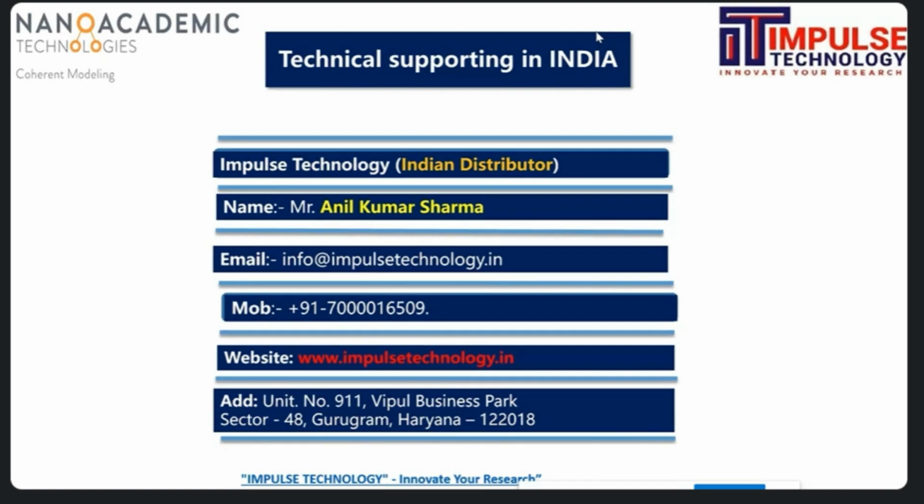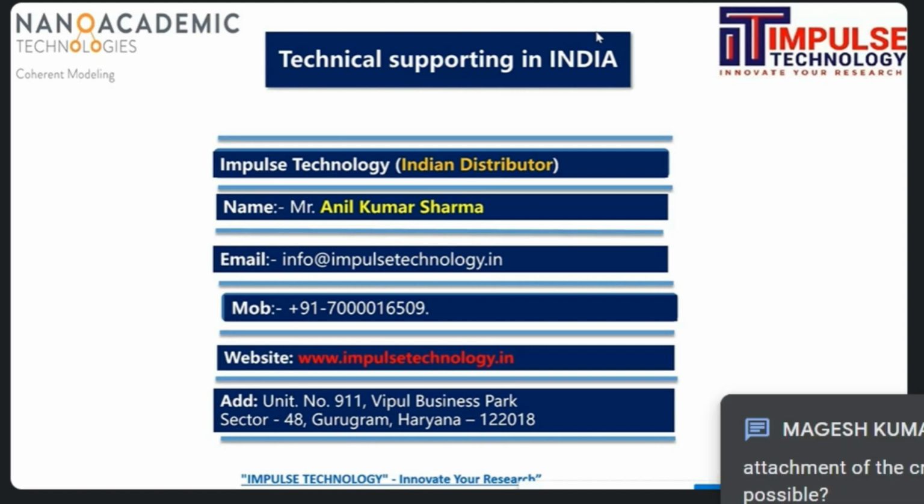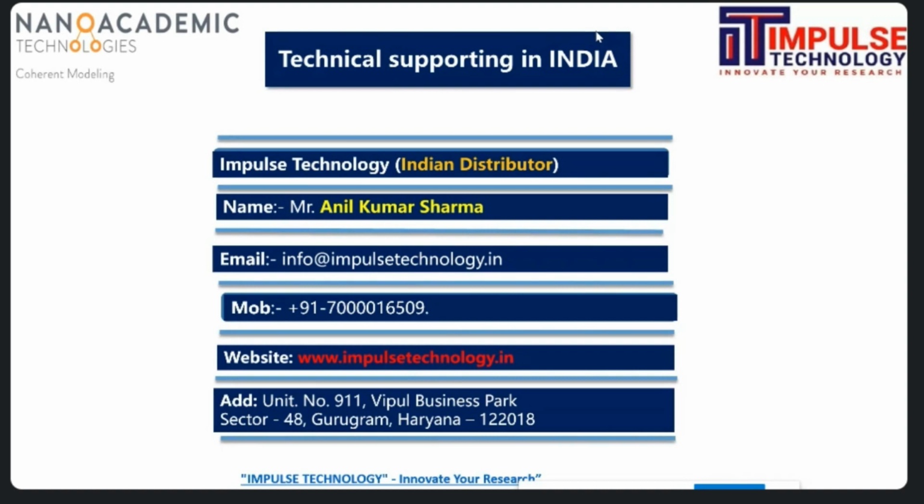Actually, that is my question. I work on experimental physics, so to start, to work in this software, what kind of preliminary things should I acquire in the initial stage so that it will be easier for me to work in this software? So you require some coordinate points of particular atoms, as well as some lattice parameters and lengths, ABC value, alpha, beta, gamma, the lattice types, and then how many atoms you want to simulate, and then theoretical DFT parameters are required.